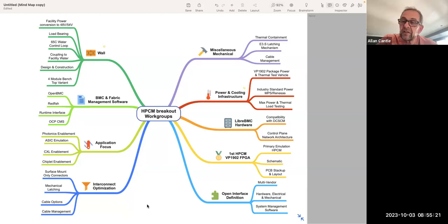To that point, at some point you must simulate and or emulate your own chip, and one assumes that all the other chiplet vendors will simulate and emulate their chips. So the idea of us starting with an emulation platform is that somebody could emulate a complete SoC with like 2, 3, 4, 5 chiplets in it, and then actually drop real chiplets in when they come online and plug them into the rest of the emulation platform.